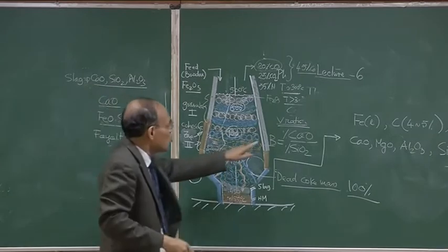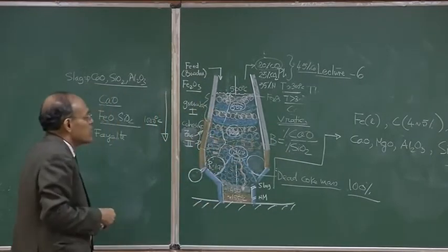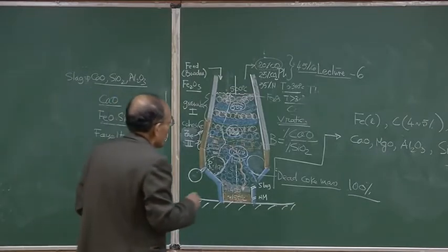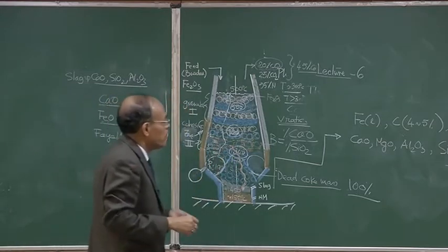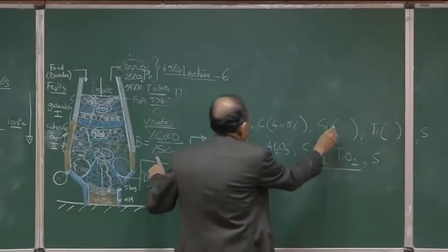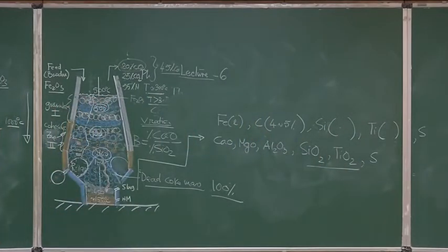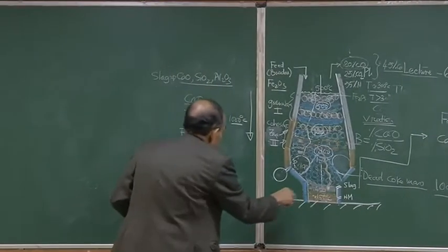Further progressive dissolution of CaO in a CaO-SiO2 system will demand more temperature, and as a result we may land up, for example, getting more silicon, because I have said that the higher the temperature, in the lower part of the furnace you are going to get more reduction of silica, which is going to land up in the hot metal phase itself.